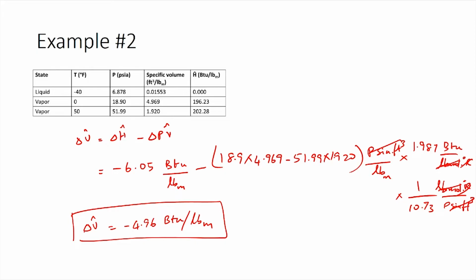The third part of the question asks us to identify the assumption that has been made. So, we have calculated specific enthalpy values without actually knowing the pressure of the final condition, which means we have assumed that the change in specific enthalpy was independent of pressure. So, this is a reasonable assumption to make for any small changes in pressure, because it is a gas and we can assume ideal gas behavior.